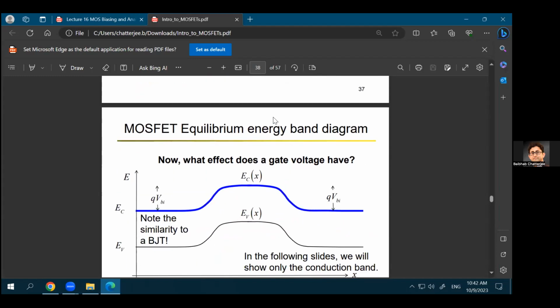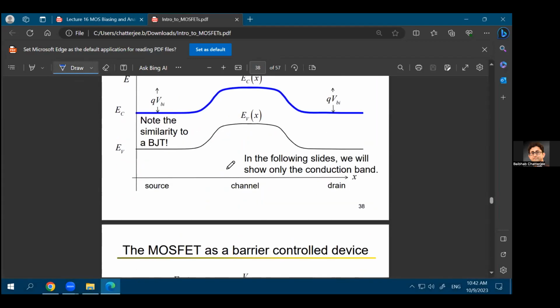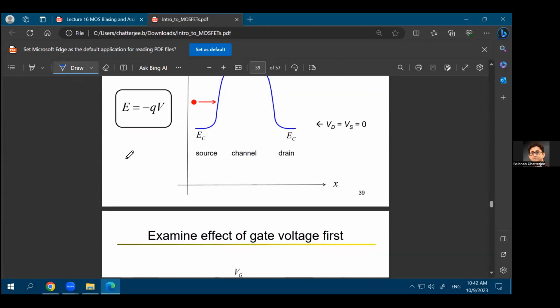Why? Because MOSFET is a more complex structure. A p-n junction diode was just a p-type semiconductor along with an n-type semiconductor. But for MOSFET, you basically have this. Let me draw it somewhere over here. So you basically have the gate. Let's call this region the gate. You have an oxide region in between. So that's the oxide. The gate in most cases will be a metal, so let's call it M as well. And then you have an oxide, and then you have a semiconductor. So that's your MOS structure: metal, oxide, and semiconductor.